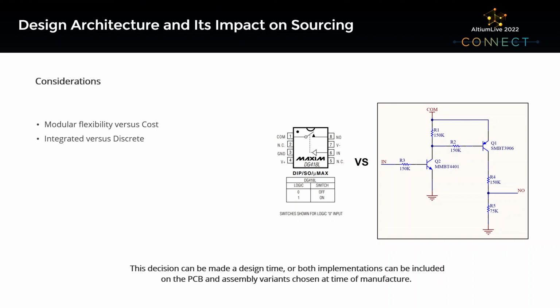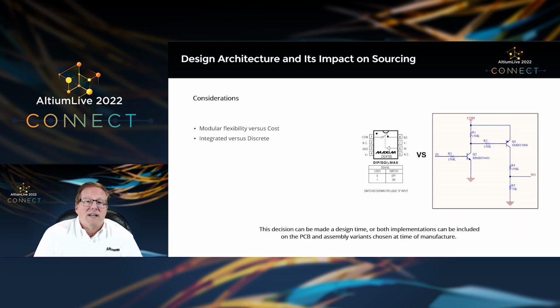So again, that gives you flexibility. If some of your difficult to find chips happen to be implemented as discrete blocks right now, you might find yourself in a better position to get through manufacturing than some of your competition. And certainly fully aware that you have more placements, you have more soldering, etc. on the right. Again, we all know that our passion for design is an exercise in constant trade-offs.